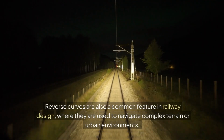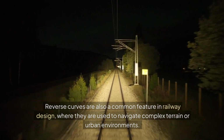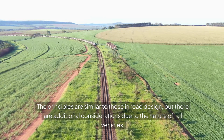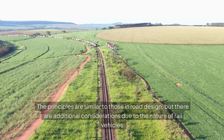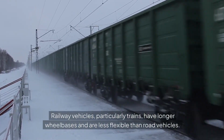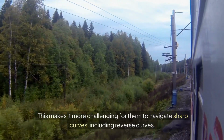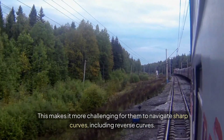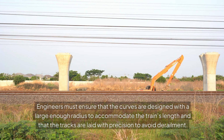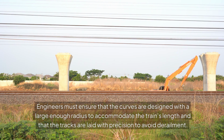Reverse curves are also a common feature in railway design, where they are used to navigate complex terrain or urban environments. The principles are similar to those in road design, but there are additional considerations due to the nature of rail vehicles. Railway vehicles, particularly trains, have longer wheelbases and are less flexible than road vehicles. This makes it more challenging for them to navigate sharp curves, including reverse curves. Engineers must ensure that the curves are designed with a large enough radius to accommodate the train's length and that the tracks are laid with precision to avoid derailment.